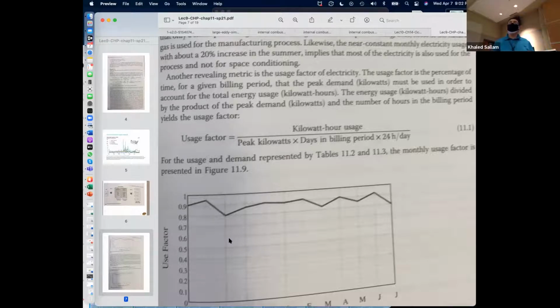And by the way, big buildings here in Tulsa, their bill doesn't just come in kilowatt hour. Their bill also comes with peak kilowatt. So the electric company, whatever it is, they monitor not just how much energy you took from us, but they monitor when you spiked up, in kilowatt. Like for example, if you have a big air conditioning system, we call them chillers, right? So those chillers that cool the air for a big apartment complex.